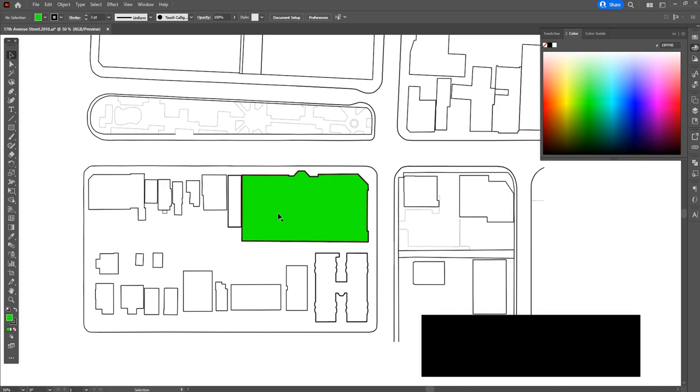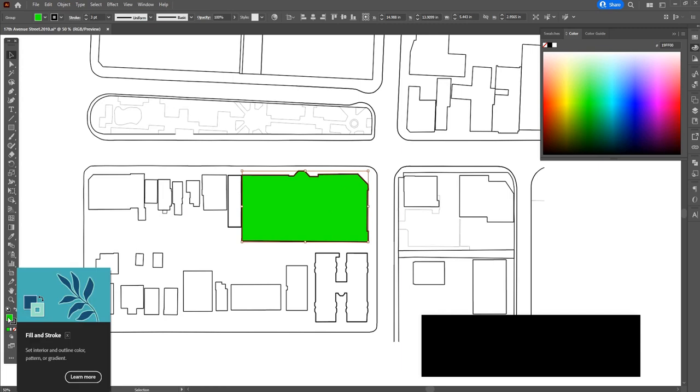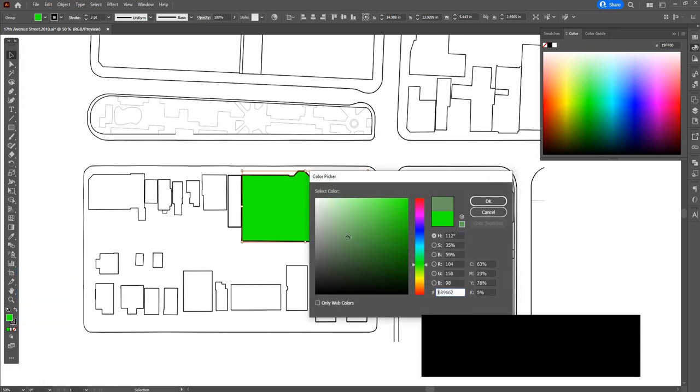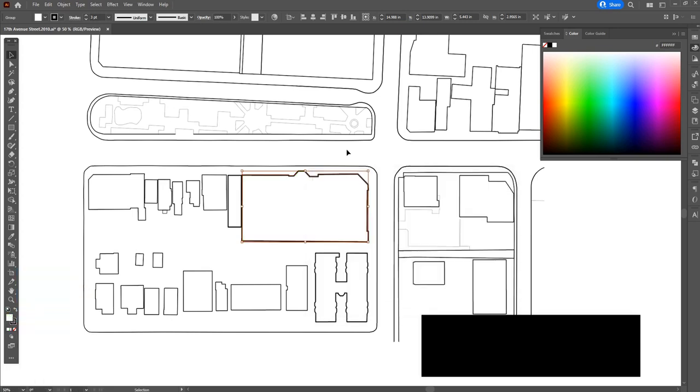Let's go ahead and adjust that so that the fill color is white instead. Left click, with the shape selected, move down to the fill and stroke, double click, select and drag to white on the color picker. That looks good. Hit OK, and there we have it. And you can do this to all of these shapes. And again, this is why it really helps that before we imported it, we made sure these were all closed polylines, so they can be adjusted in fill and stroke as a closed shape.